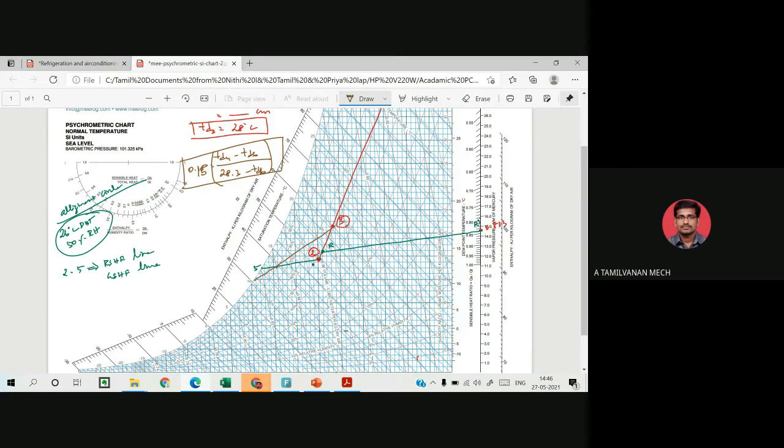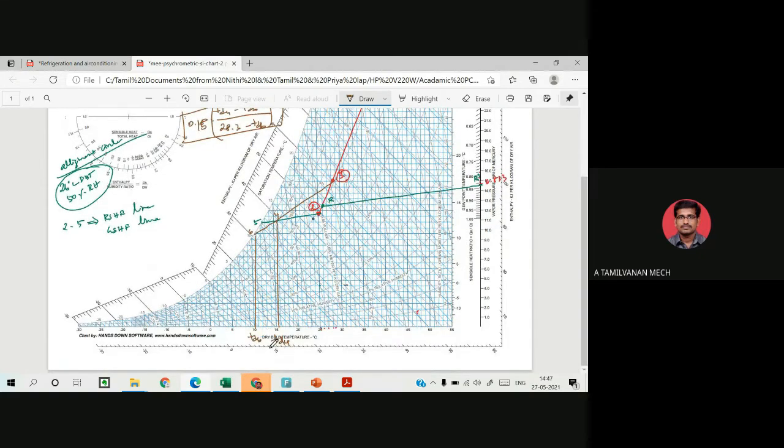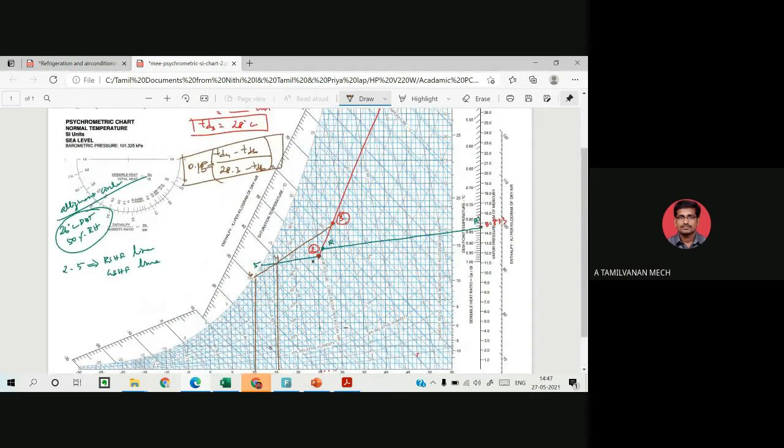Last time this line was slightly larger. Again you note the temperatures TD6 and TD4, and substitute them in the bypass factor equation to see whether you get 0.15. It is just a trial and error measurement. You repeat the process until you get exactly 0.15.